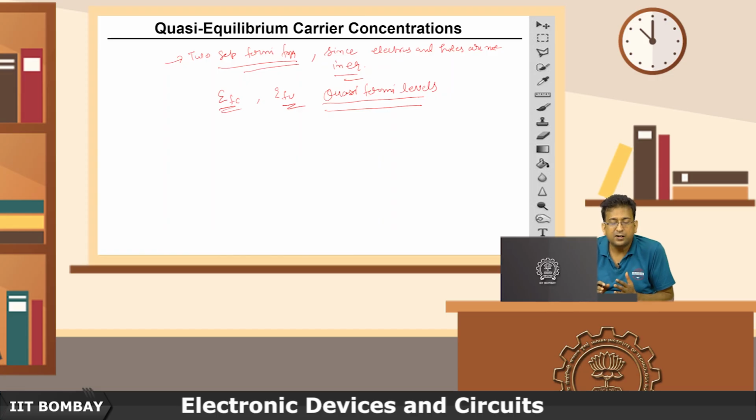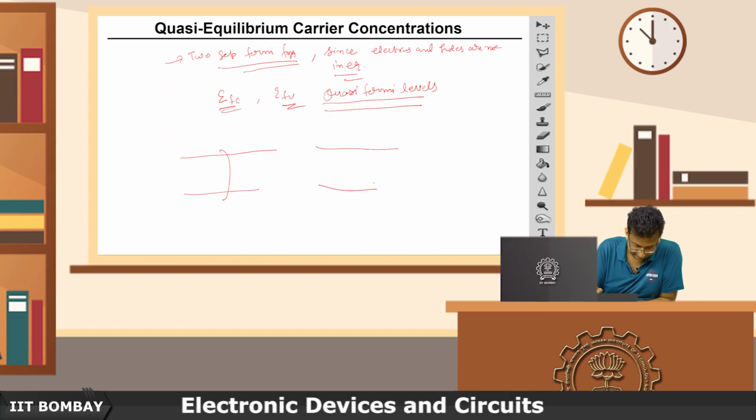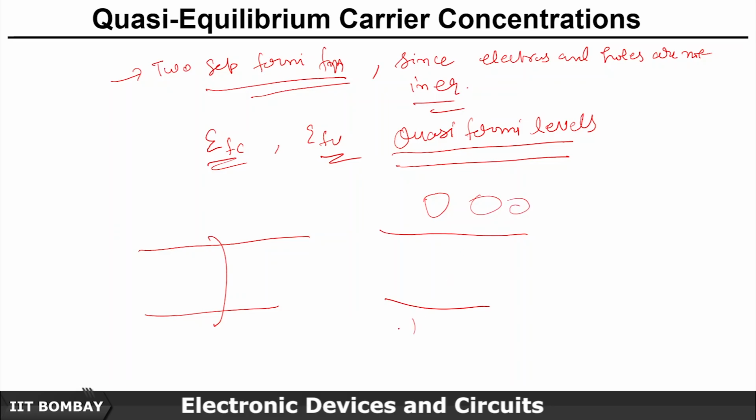And since the recombination rate, the rate of equilibrium between bands, tends to be much slower than the energy excitation rate within each band, this rate of recombination is much slower than the things happening within the conduction band and the valence band. So there is a mismatch. Therefore the equilibrium case cannot be applied, things will be different, and this situation is known as quasi-equilibrium.